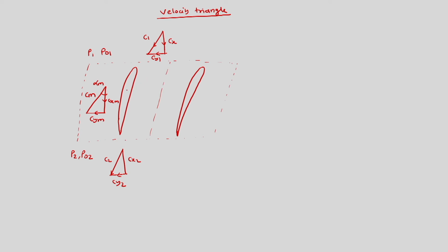Now we can show the forces same way as what we did for turbine. This is Fy, this is Fx. So this becomes the resultant Fr. Now here we again need to decompose them into lift and drag. So this is lift and this is drag. And this resultant is Fr. So we can continue by applying momentum equations for the compressor cascade.